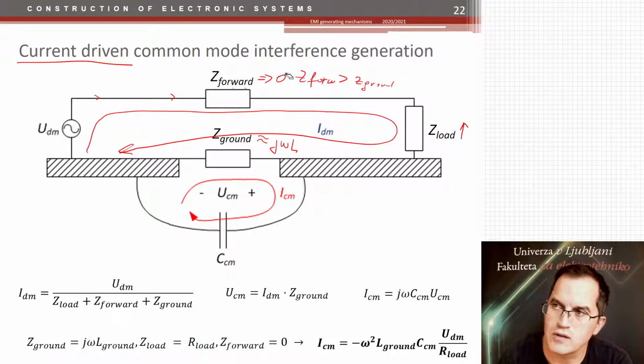So it's not going to 0 if I'm very, very precise. It's even larger than the Z ground, but we don't care about it that much because the different parts of the PCB all contain ground. And ground has a large area as well, because all the PCB has some ground everywhere.